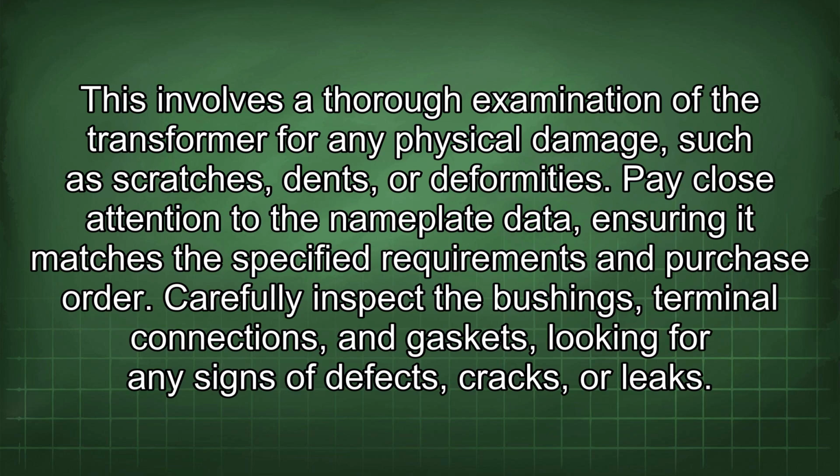This involves a thorough examination of the transformer for any physical damage, such as scratches, dents, or deformities. Pay close attention to the nameplate data, ensuring it matches the specified requirements on the purchase order. Carefully inspect the bushings, terminal connections, and gaskets, looking for any signs of defects, cracks, or leaks.